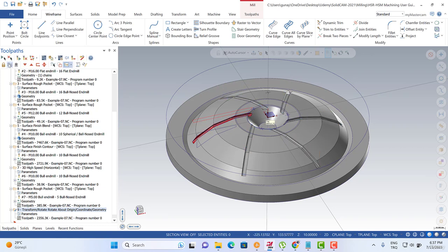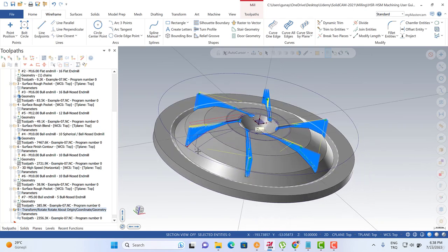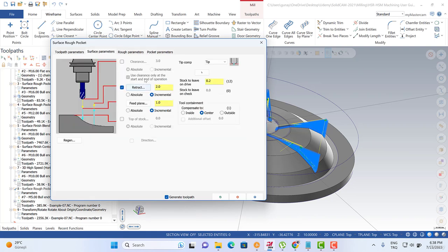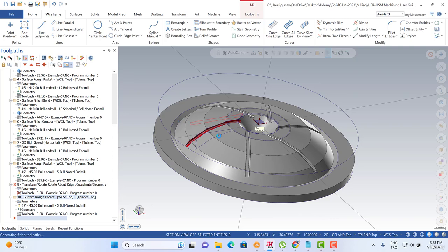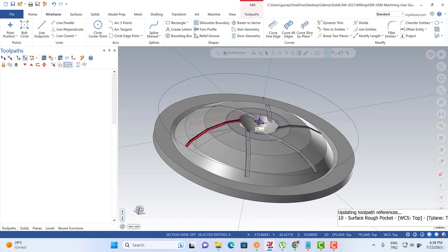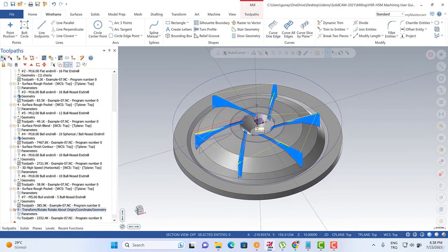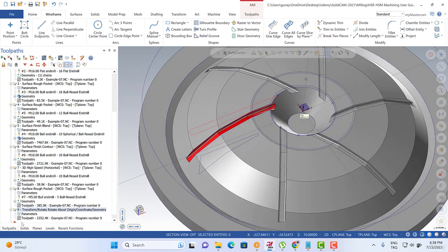Okay, so yeah, you know that there is some problem here. Maybe we should turn to here, and we can activate our coordinates plane as 5 mm with absolute coordinate, and then we can recalculate our toolpath, and then we're going to solve that problem, I think. Yeah, it's perfect. And after that, you can easily create your finishing process, for example.